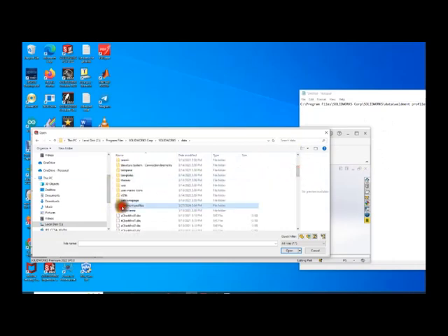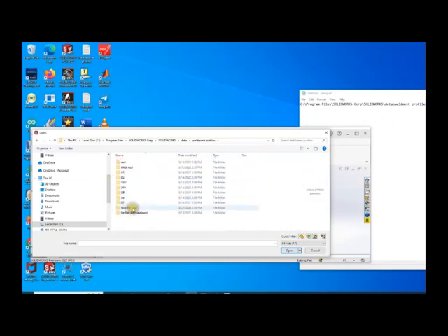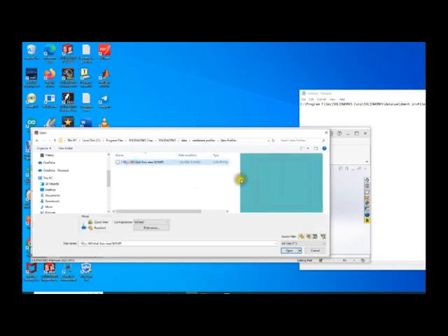right here, and mine in new profile. That's where I put it, new profile right here, and this is the guy, and it shows something here. The only thing I don't like on this Weldment profile is that on galvanized steel there's a round curve here. Everything looks good, but it's not round here in the corners. It should be. We can fix that in a second as well. Open.